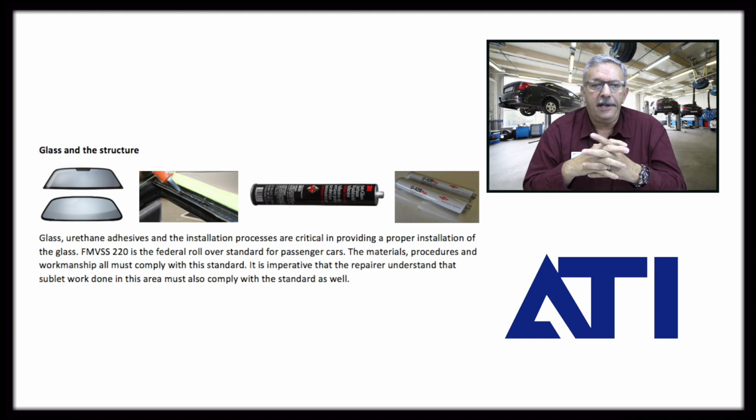Again, that's not something for today's topic, but that is something that we're going to be looking at in the future. In an effort to cycle the vehicle quickly through the repair process, we've got people coming out with all of these quick cure adhesives. We need to know that that adhesive will withstand the requirements of FMVSS 220. If it doesn't, they shouldn't be using it.